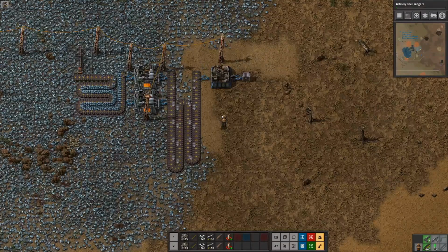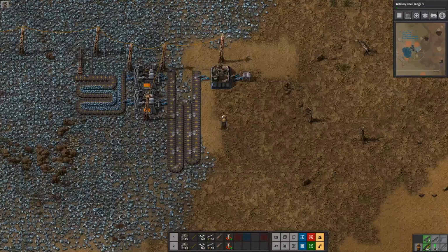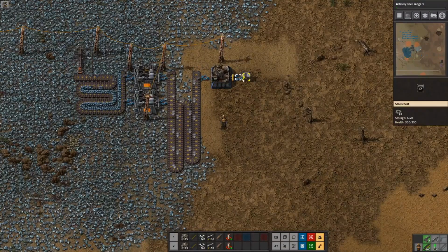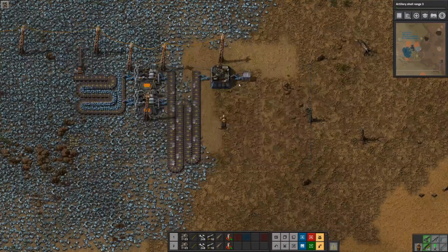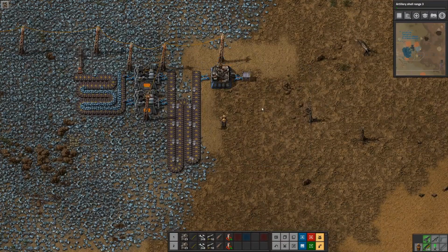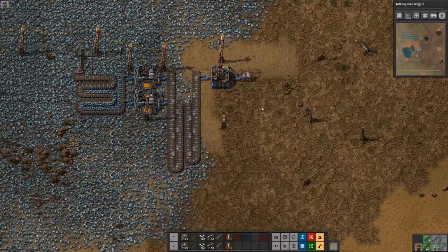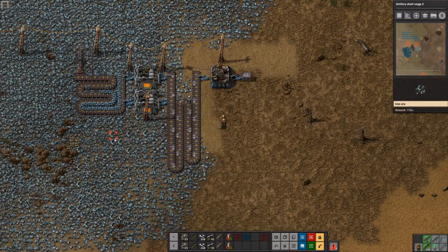So what did we notice? I affected the constraint, or the bottleneck, and I improved its throughput a lot. And what do we notice about the overall throughput here? Well, we may not have been paying attention to that, but I can tell you that the gears coming out of here are coming out much, much, much faster, simply because these guys are working much faster.